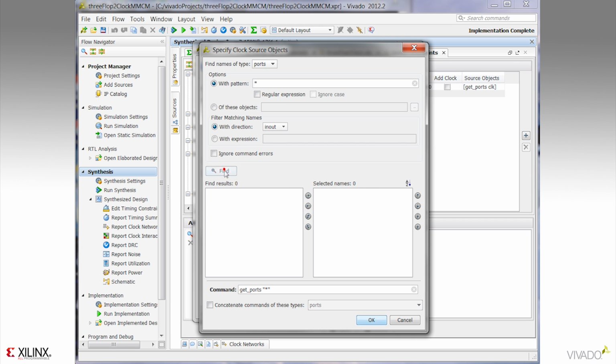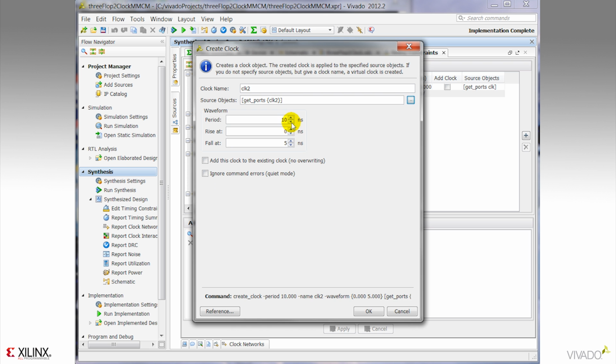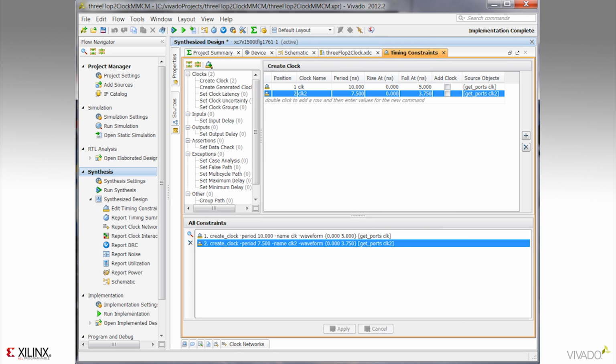Remember that all clocks are assumed to be related by default unless constrained otherwise, so you need to analyze the paths between these domains, make sure they are properly synchronized if they're not truly related, then add in the appropriate constraints to mark them asynchronous. Otherwise, any paths found will be valid and will affect the placer, the router, and logic optimization results significantly.